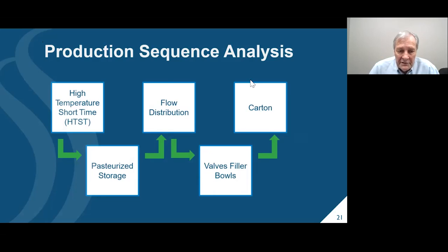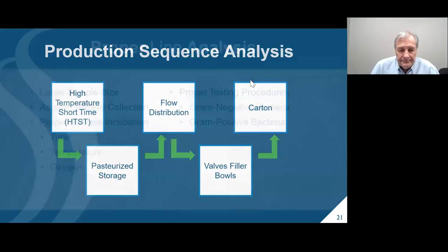It's possible that the inner wall can create a crack where you get milk solids and other material between the walls of the tank. When the tank is empty, the crack recedes and you can't really find the crack. When the tank is full, the crack opens up, and what we used to call in the dairy industry applesauce is squeezed from the interior of the storage tanks into our product, creating contamination.